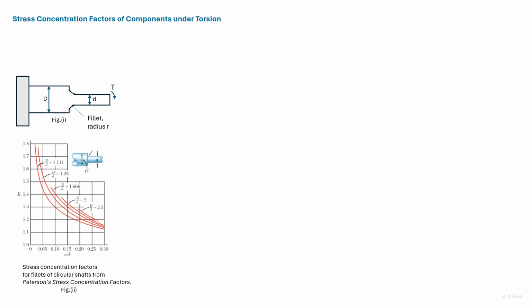Stress concentration factors are obtained using the mathematical theory of elasticity or experimental methods such as the photoelastic method. They are given in tables or graphs as the one shown here. Stress concentration factors are found to be dependent on ratios of geometric parameters and not on dimensions or the material of a component.